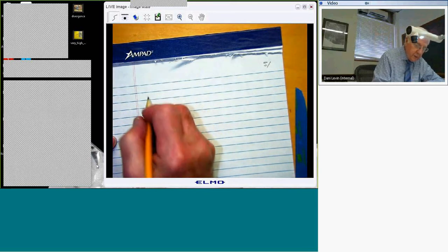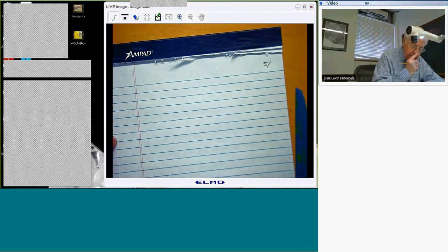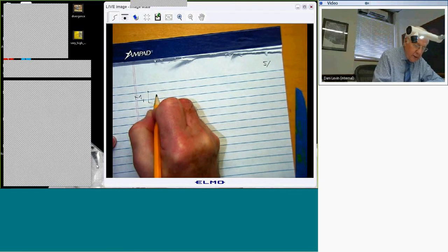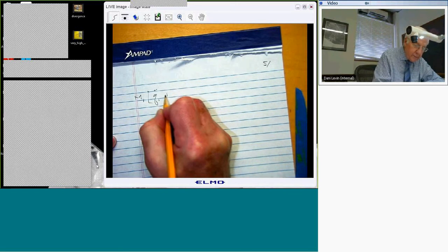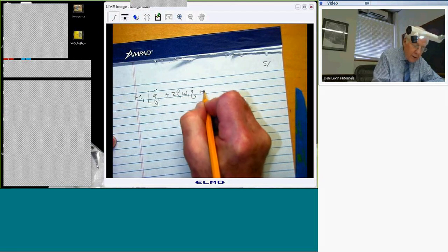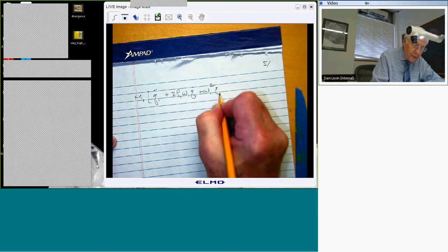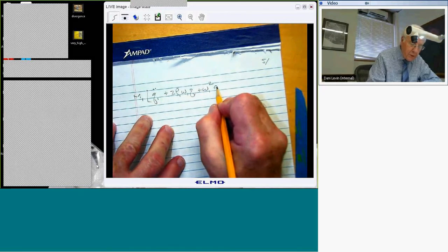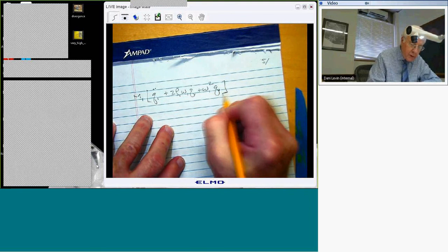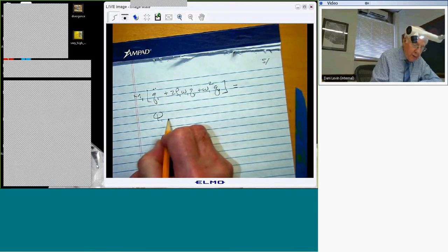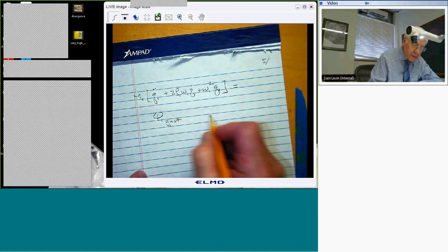It's m sub 1, p sub 1 double dot, and so forth. Only properties of the first mode appear in the first mode equation as far as the structure is concerned. But then on the right-hand side, we have Q1 due to the gust plus Q1 due to the motion.